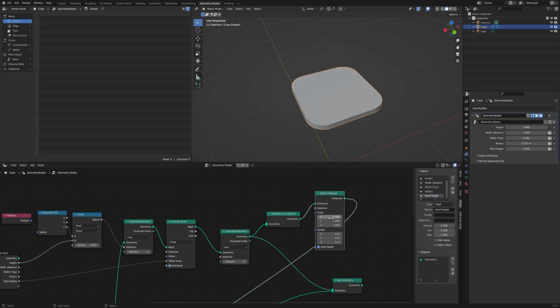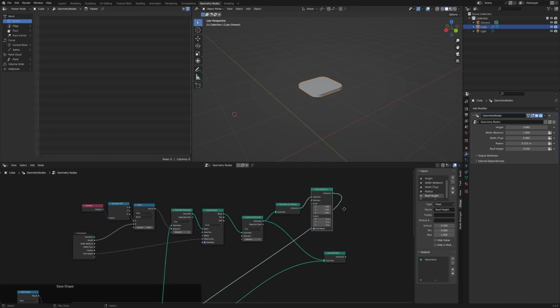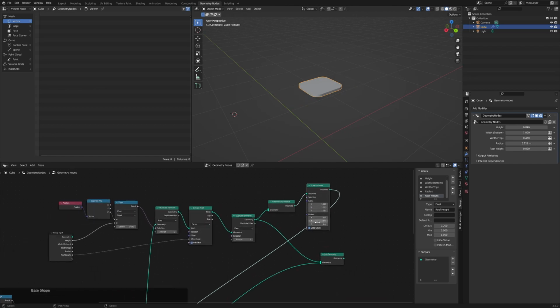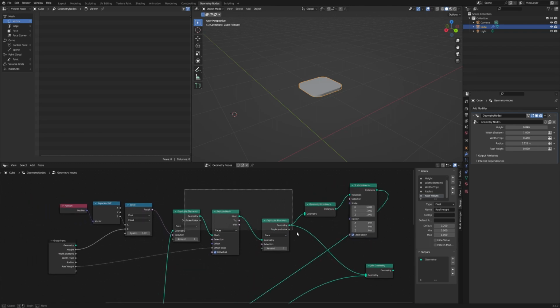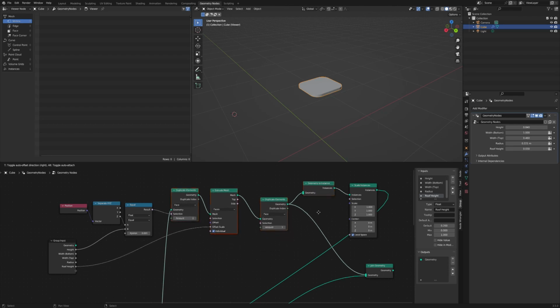So that means then when I get my instance, if for example I scale in the Z axis, woohoo, it goes all over the place because my origin of that scale is still set to be 0, 0, which is just down here. So for example, if I change X-axis, that doesn't matter too much, but you'll see it's now treated as one single object. So there's a couple of things we need to do. First thing we want to do is set the center. So the center of the offset is actually going to be our height.